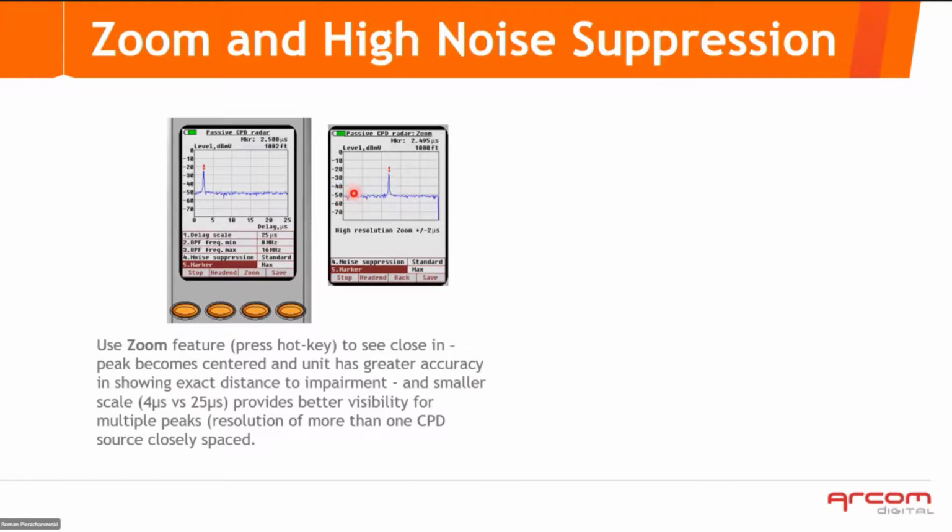Here we've got a relatively high noise floor, minus 50 dB. It's a high noise floor. When you are searching for low peaks before the return amplifier, these peaks may be minus 50, minus 40 dBs. So it's more comfortable to work when the noise floor is minus 65, minus 70. Sometimes it's just minus 80.